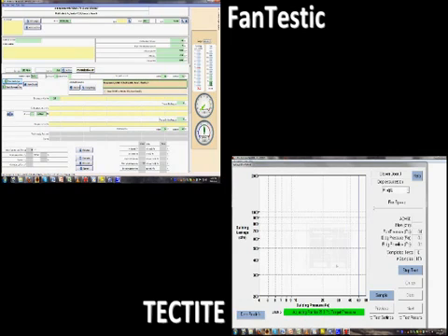In order to complete an automatic test, you'll need to connect your gauge to a computer. The DM2 connects with a USB cable, and the DG700 with a serial cable. You'll also need to connect your gauge to a fan for automatic fan control, using either an Ethernet cable for a DM2 or a 3.5mm fan control cable for the DG700.